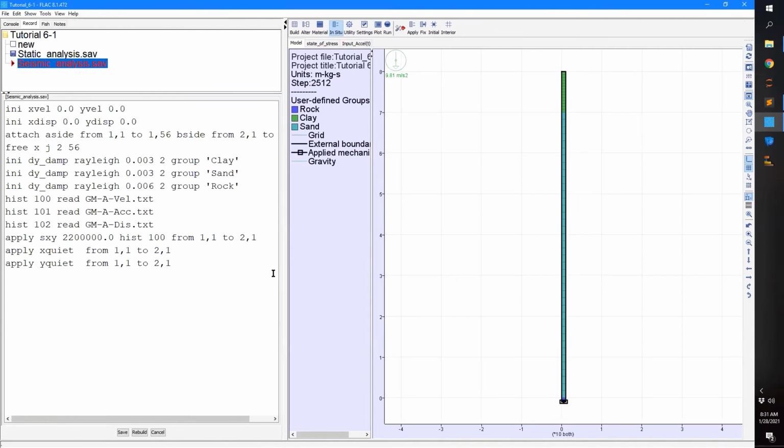Well, at this particular stage, we're pretty much ready to go. A few last things that we want to do is set dynamic on and mechanical on, or set dynamic on, mechanical is always on. That would be a key item. And now at this particular time, we could solve for the 90 seconds. What I want to do is let's not solve for the whole time. It might take a little bit of a while.